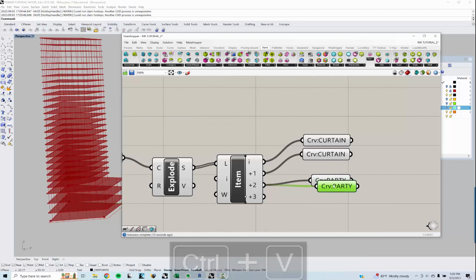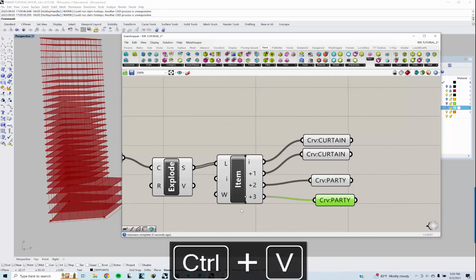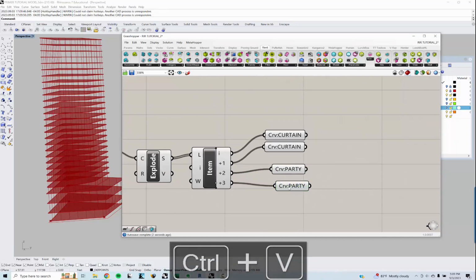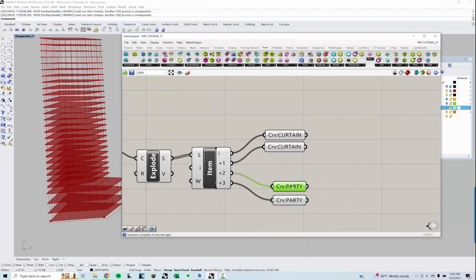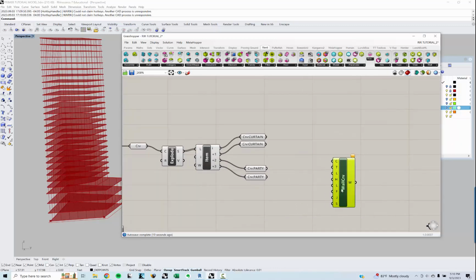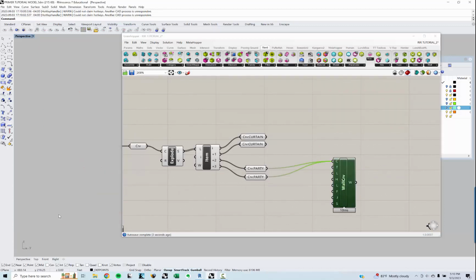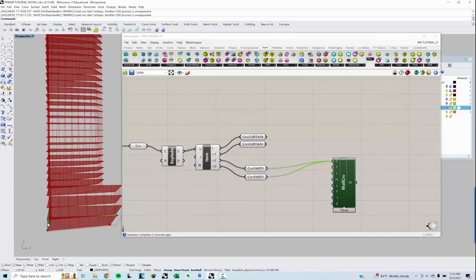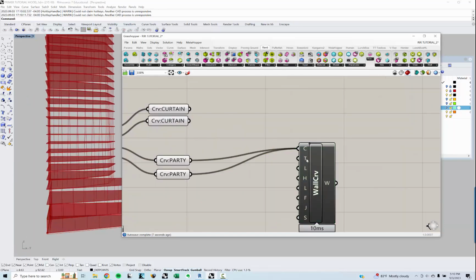And then I will do the same for this one, which is the back. So let's do the party walls first, because they're kind of the most straightforward. I'm going to come into this wall and do add wall curve. Super straightforward. All I've got to do is plug in the curves that I want the party walls to go on, and immediately it just starts generating geometry.